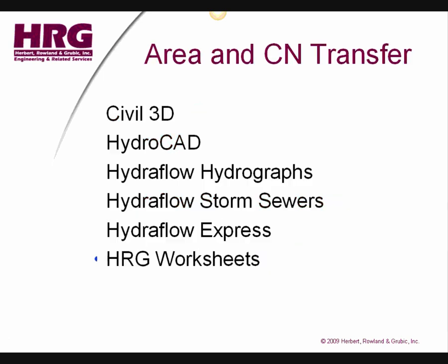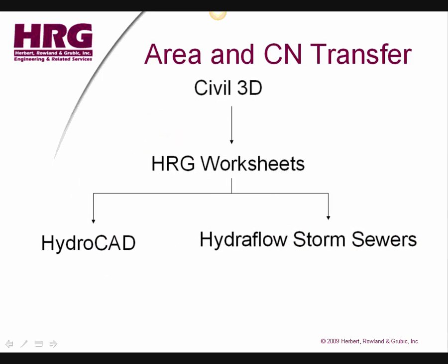What we're really going to focus on today are AutoCAD, HydroCAD, HydroFlow storm sewers, and the HRG data flow worksheets. So how this is going to work is we're going to determine our areas using AutoCAD or Civil 3D. We're going to use the HRG worksheets, again, the key part here, and we're going to push that data directly into HydroCAD and HydroFlow storm sewers. No manual editing or manual data entry at all.